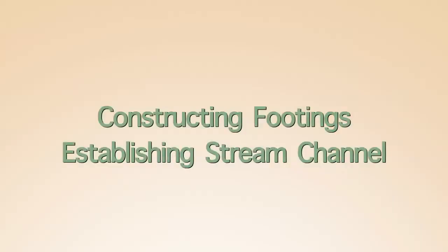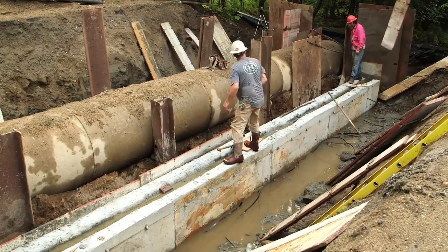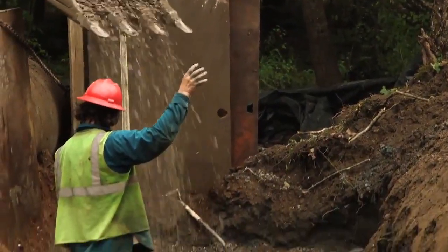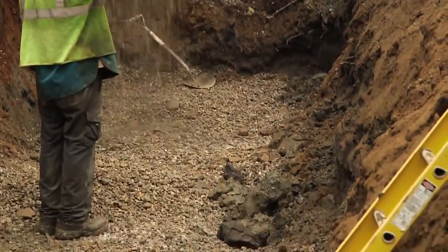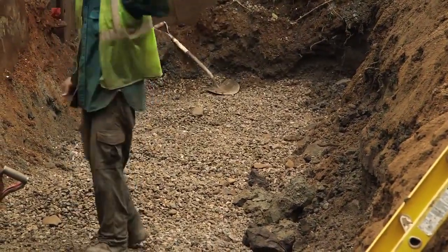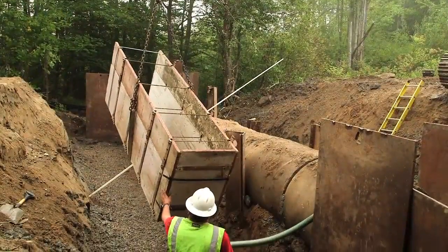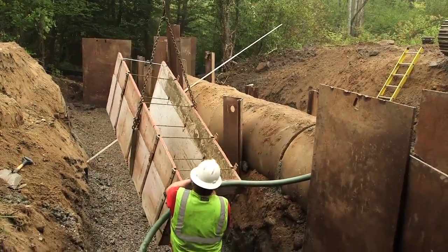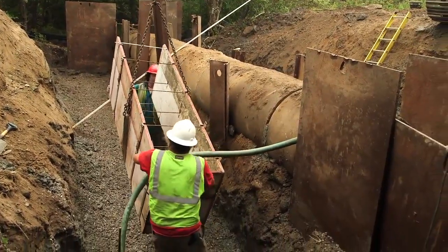Constructing the footings and establishing the stream channel. The footings for this were poured in-place concrete. The footings were placed on a firm, well-drained base material. The amount of well-drained base material that has to be brought in depends on the existing material below the footings. If the existing material is not suitable, it may have to be excavated and replaced with a well-drained base material.